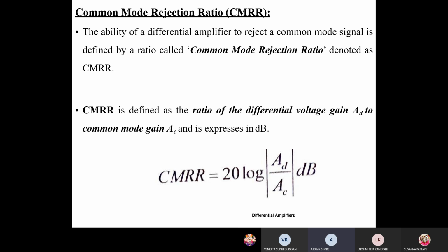If any disturbance occurs within the signals, the value will go up and down. At that time, many disturbance signals or noise signals appear as a common input signal to both the input terminals of the differential amplifier. Such a common signal should be rejected by a differential amplifier.